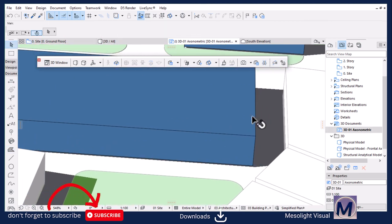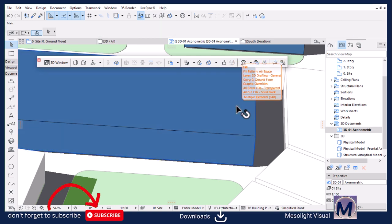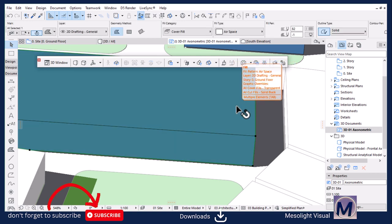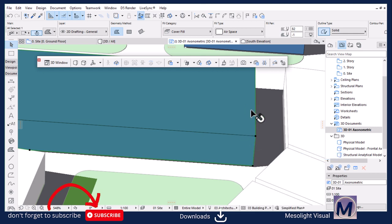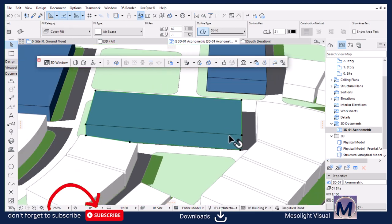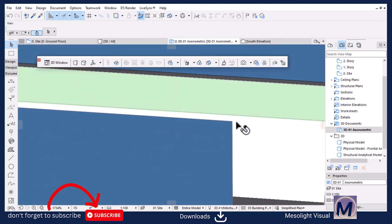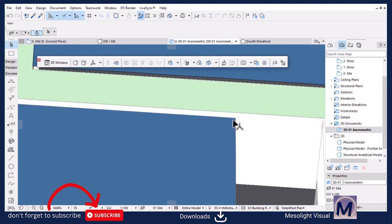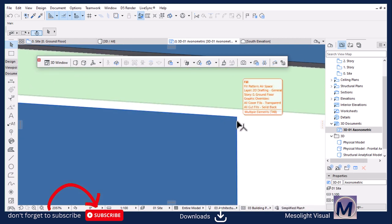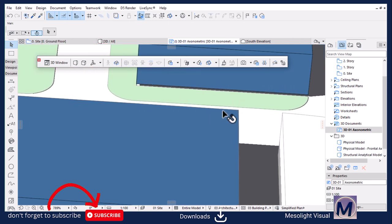So there's nothing changed, but we need to tap to access the fill and select it. Oh, sorry. Let's tap again, fill, select it, and then right click to display order and bring it to front. Bring it to front. There is nothing yet, because you know what? We have graphic override that is overriding the settings of our fill. What we need to do is to set a rule for the fill, specifically for this.